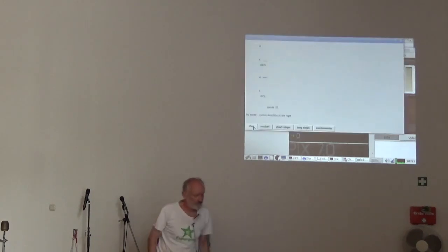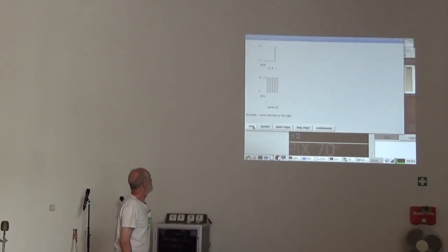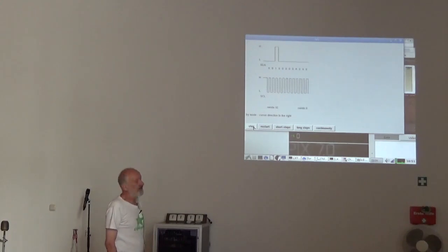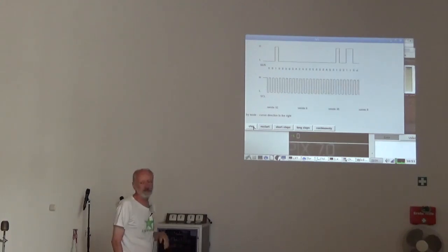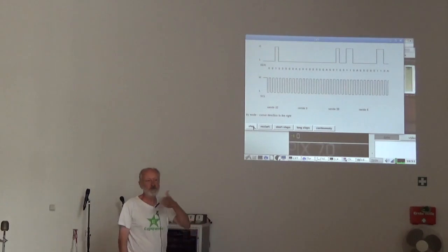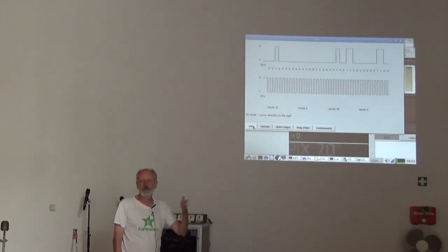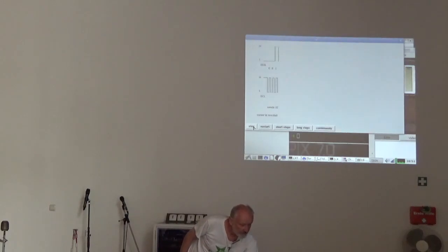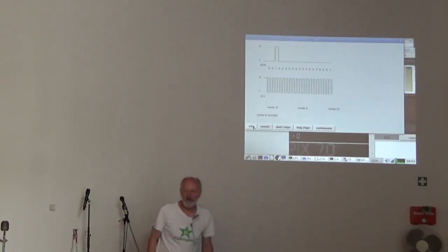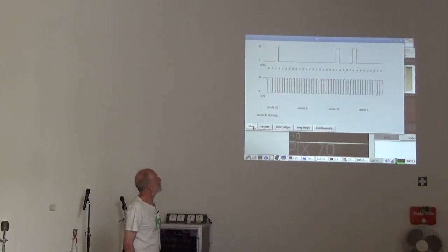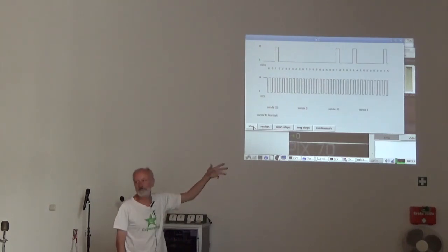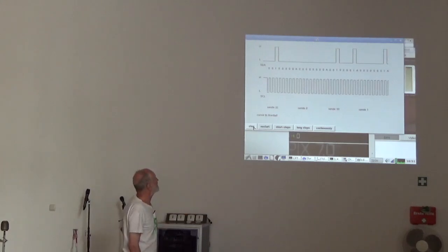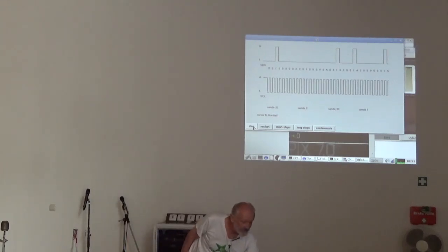Then I send a command that the cursor direction is right, because for example for Arabic or Hebrew letters it can move in the other direction, and it moves the cursor to line start. After power off, normally the cursor is already at line start, but I can explicitly do that.